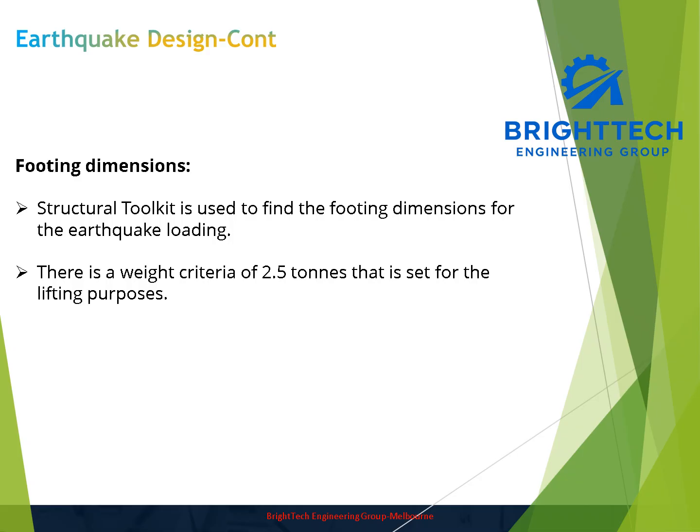So the pieces are prefabricated in the manufacturing area. When we manufacture them and let them set, after the manufacture is completed, we need to transport them to the construction location and then lift them and place them in the location. So based on the requirement by the client, we are limited to 2.5 tons for each piece.